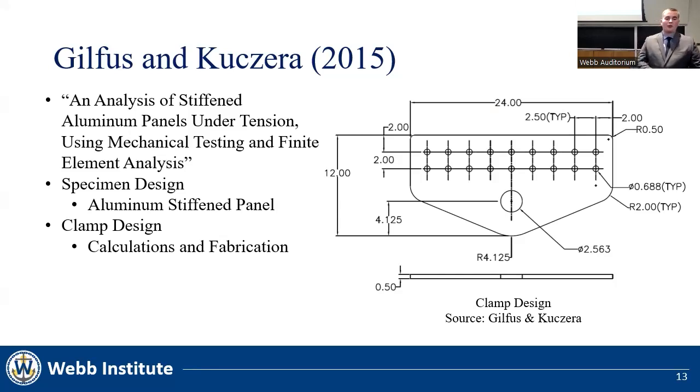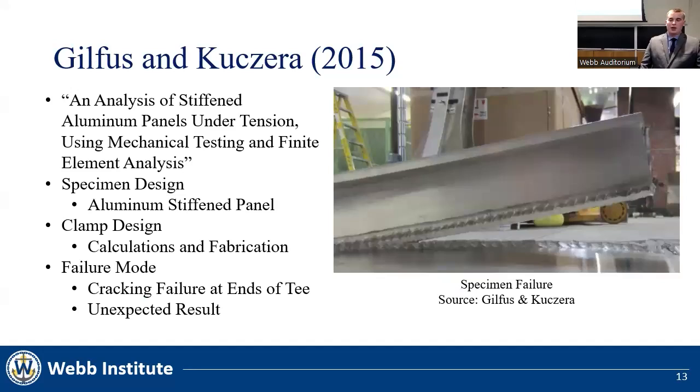Their testing did, however, yield some interesting results, which are attributed to the additional stresses acting within the material. Their 4 samples failed at the ends of the stiffener, pictured off to the right, as opposed to the narrow section of the dog bone. The stiffener is seen actually peeling off the plate, and the reason for this might be the biaxial loading, as the welds were not full penetration welds, and when strain is transferred from the stiffener to the plate, membrane stretches are induced and a bending moment is created, which is consistent with the shear at the end of a fixed beam.